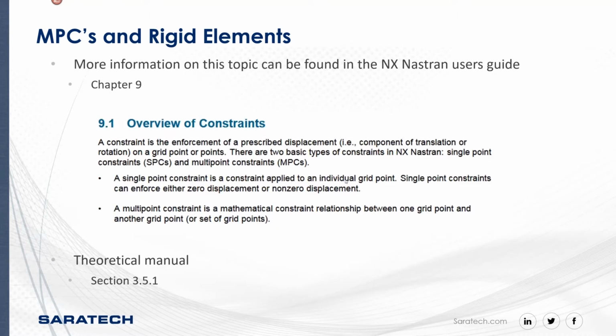So, more information on MPCs and rigid elements. Some of the information in this slide comes from the NASTRAN User's Guide, Chapter 9. And there's also more information in the theoretical manual as well.